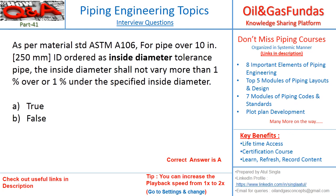The purchaser can accept up to 1% over and 1% under the specified inside diameter. Because it is impossible to maintain uniformly the same ID throughout the pipe, these clauses give some provision to accept the variation from the manufacturer. So 1% over and 1% under is acceptable as per these standards.